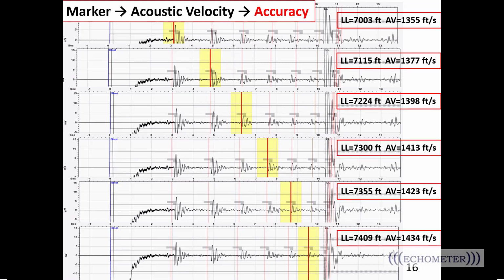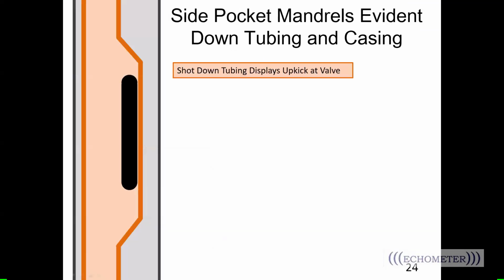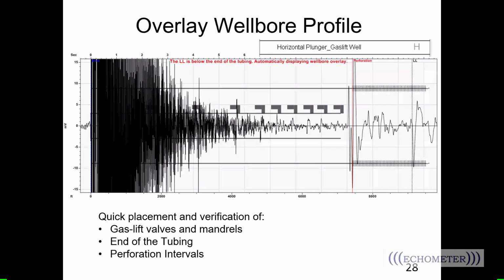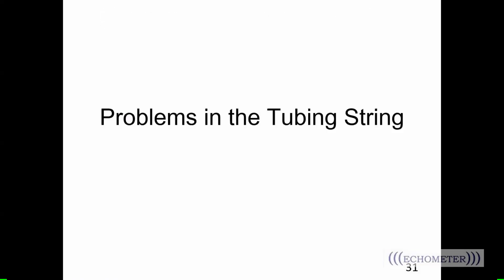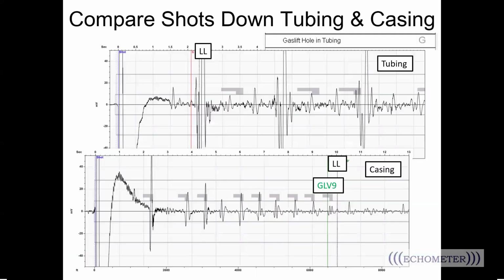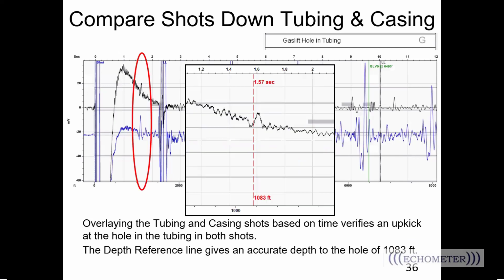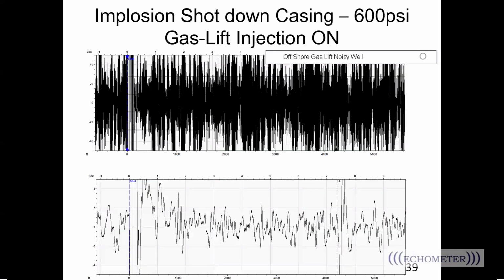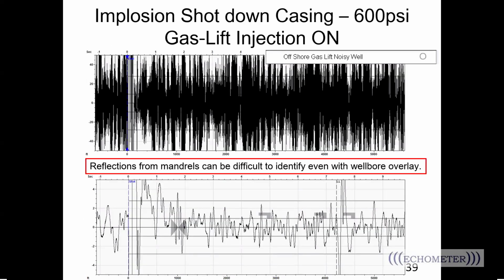Well, when we shoot the fluid level, we measure the pressure buildup. The pressure buildup is measured for up to 15 minutes. So anytime you shoot the fluid level, if you're losing pressure and it's supposed to be held, then the pressure buildup test will show a decrease or drop in pressure.